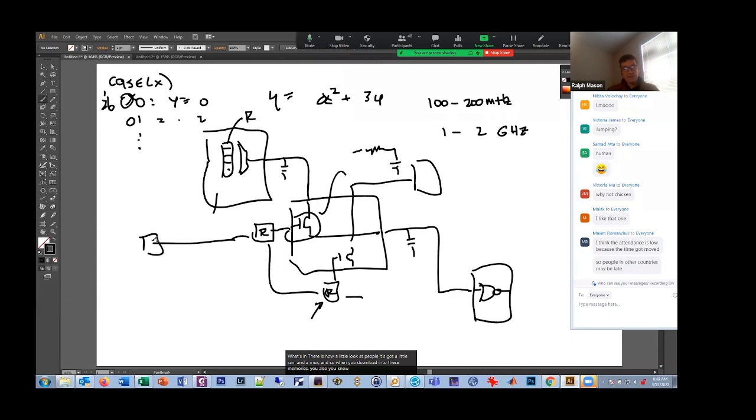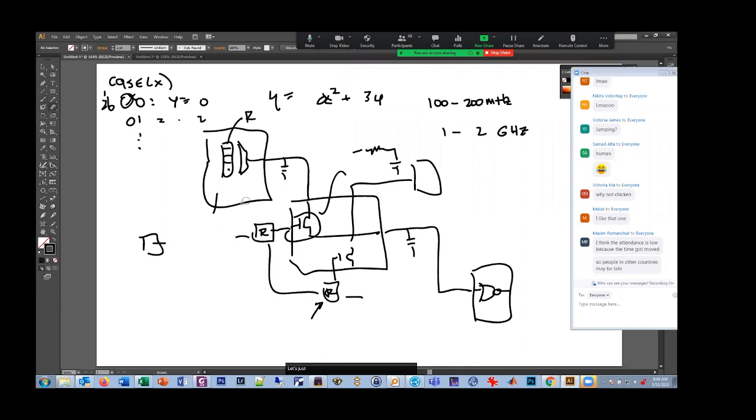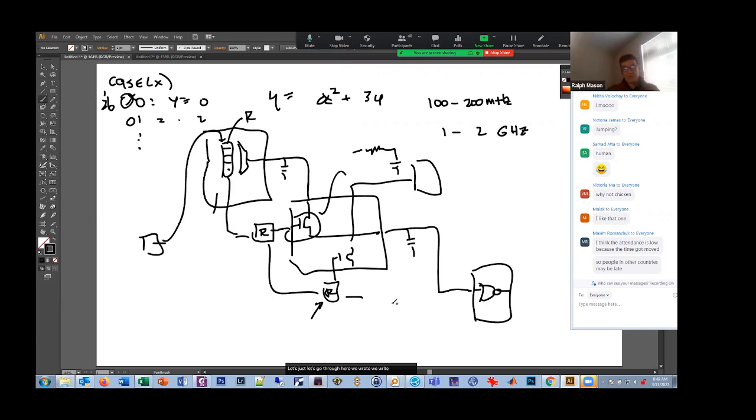So yeah, it loads in. It's kind of like this sequential path. Let's go through here, and we write all those. We write these. So by downloading your bit file, you're programming all these lookup tables to form the logic, and you're programming these switches to make all the connections between them. This is kind of cool. So by downloading this, you can change any of the logic, and you can change any of the configuration for the wiring. That's the basic idea behind an FPGA, how you can make any kind of functionality.